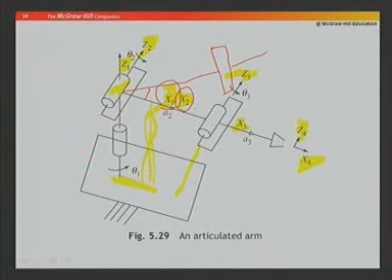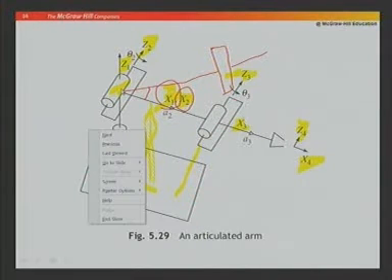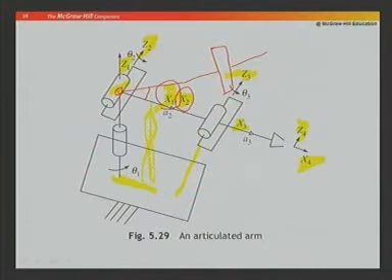I will give input to control this robot. So, theta 1 is a joint variable. So, if you look at your table, we put theta 1 as a variable. Now, A1 is the distance between Z1 and Z2. So, again coming back, there is no distance here, they are intersecting. So, A1 is 0.